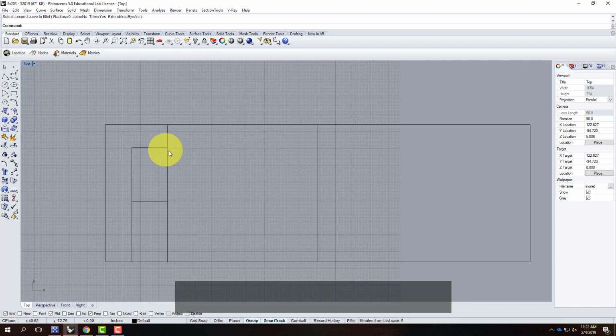By the way, in Rhino, when you're done with a command, if you right-click, you will repeat the last command. So I'm back into Fillet, and I can pick this line and this line. My radius is still 0. Once again, I'll right-click to repeat the last command, there and there. I'll right-click one more time, there and there. And it gets down to just this particular window.